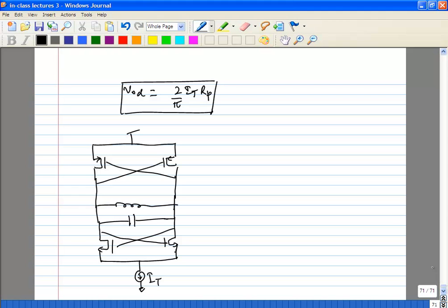Earlier you only had an NMOS pair, you are now adding a PMOS cross coupled pair also. So you are effectively flowing the same current through the PMOS also and getting more negative resistance for the same current. So now your negative resistance is -2 over GMN plus GMP. That is one thing.